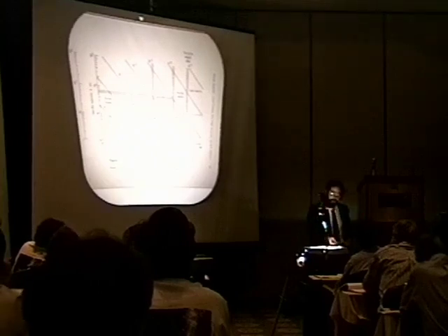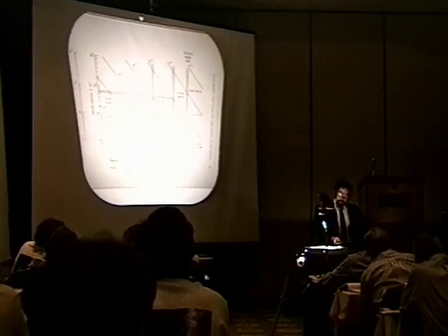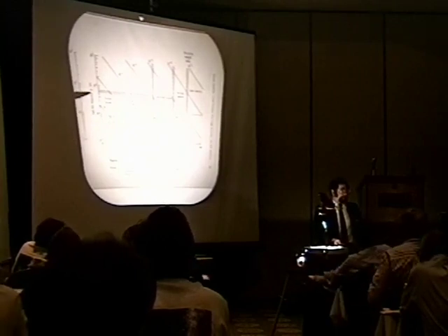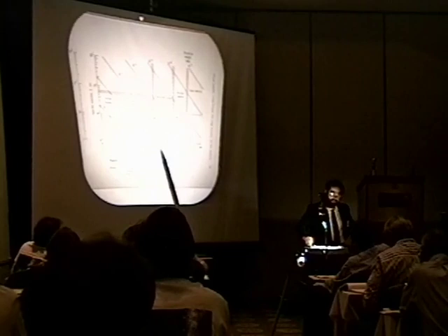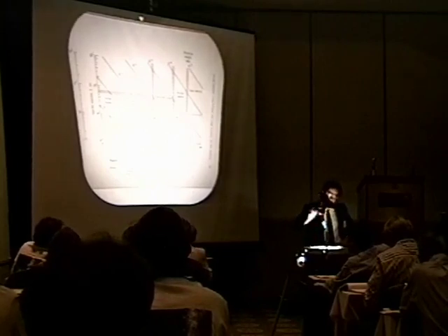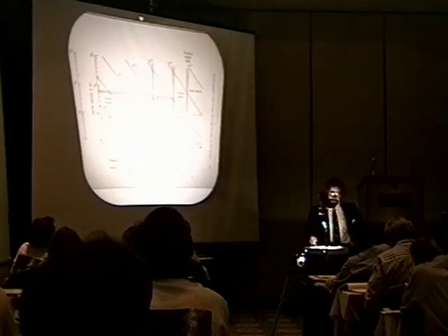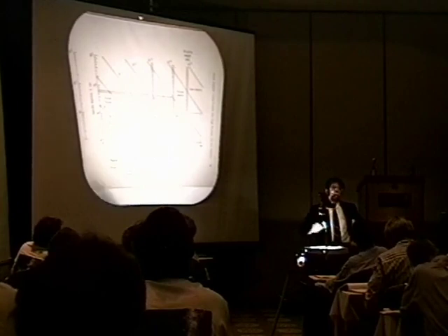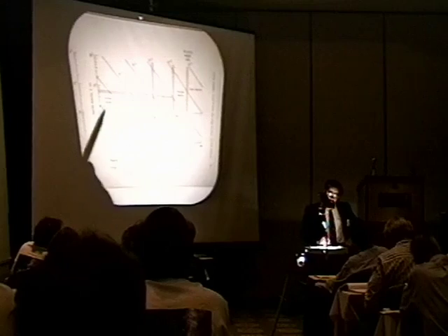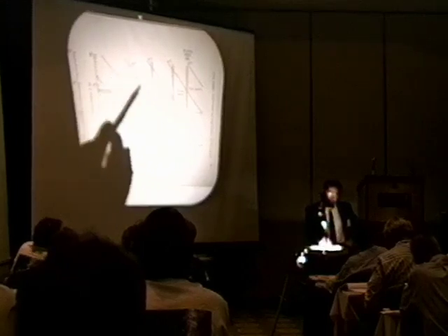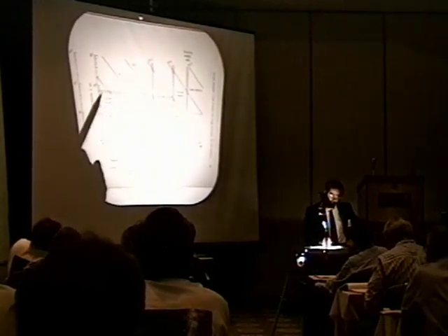Basically, we have different parameters characterizing space engines. And they are specific impulse, which I've already discussed, which is exhaust velocity, and specific mass, which is the power density, mass per kilowatt electric in the case of electric engines, but in the case of non-electric engines, to make a continuous comparison here, it's the exhaust power, the power in the exhaust. Okay? And we have thrust-to-weight ratio shown by these parameter lines: 10 to the minus 5th thrust-to-weight ratio, 10 to the minus 4th, down to 1.